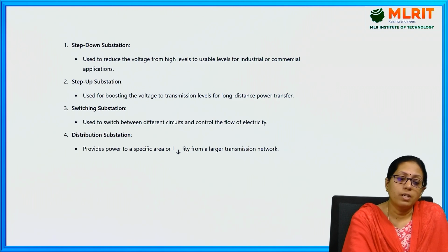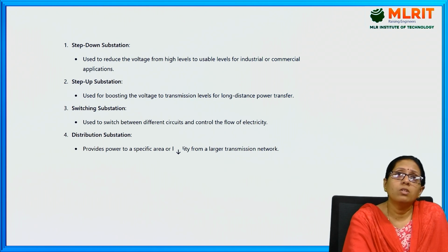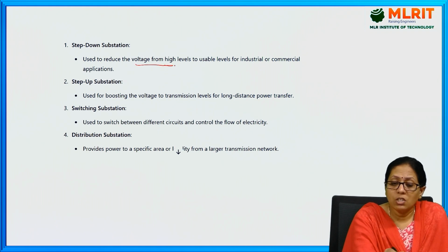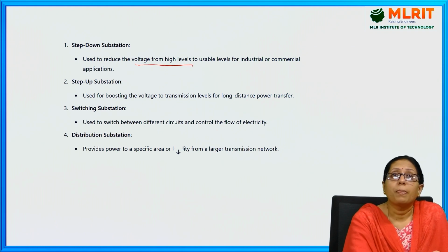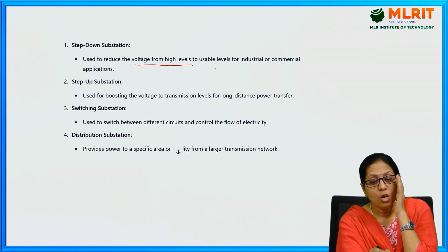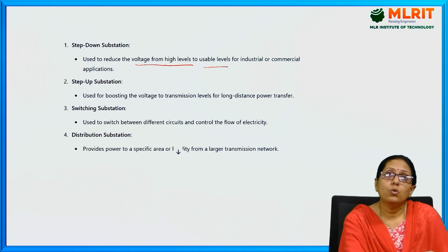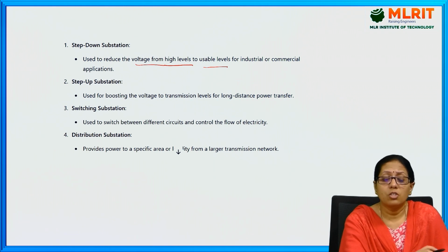The first one is step down substation, step up substation, switching substation and distribution substation. So, first one, step down substation. It is used to reduce the voltage from high levels to usable levels of the industry or the commercial applications, commercial buildings.